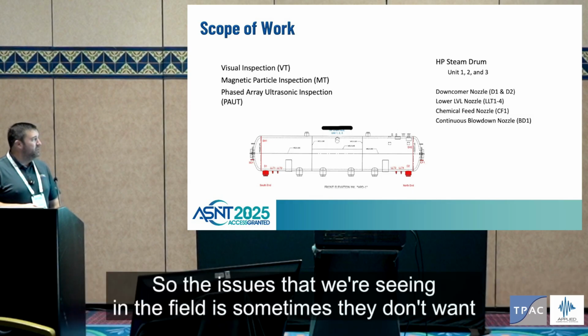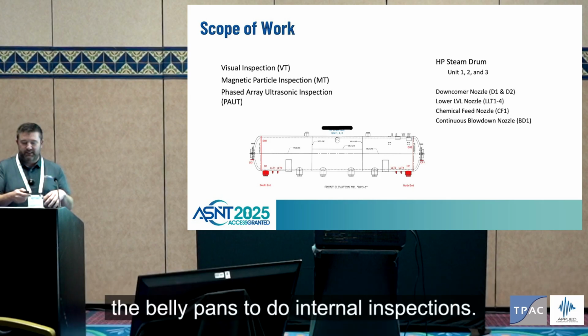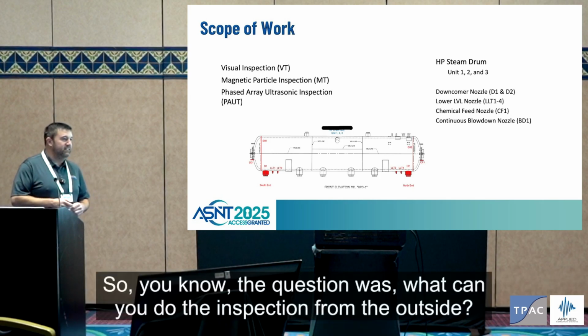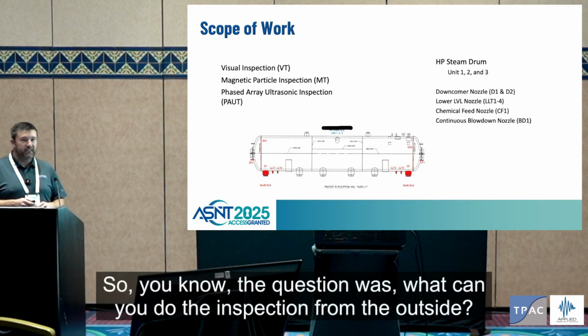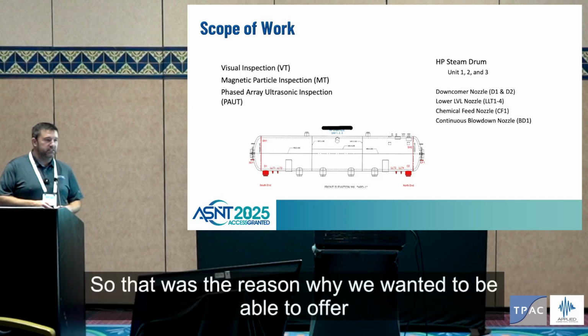So the issue we're seeing in the field is sometimes they don't want to remove all the internals to create a confined space, to take out the belly pans, to do internal inspections. So the question was, well, can you do the inspection from the outside? We can try, phased array technology is capable. So that was the reason why.